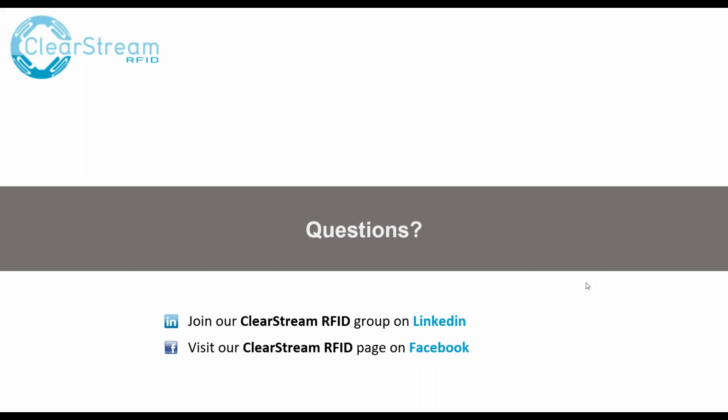Like the demo today, I had it at 10,000 milliseconds or 10 seconds. The tag has to go away for 10 seconds and not be seen by the reader, which is always actively scanning for those tags, to then be assumed that it's gone. And at that point, based on the settings, you could report it again or report it as a not visible event to the endpoint.